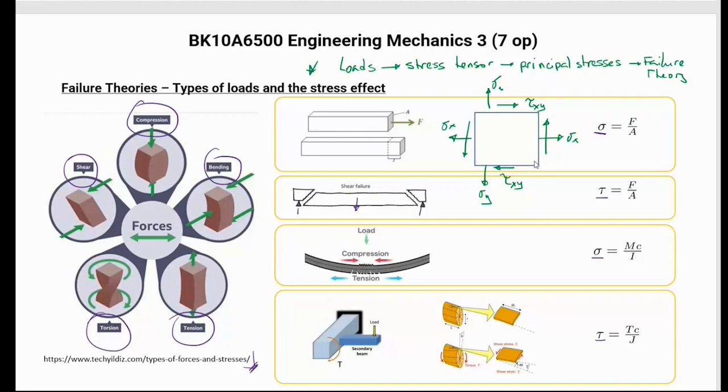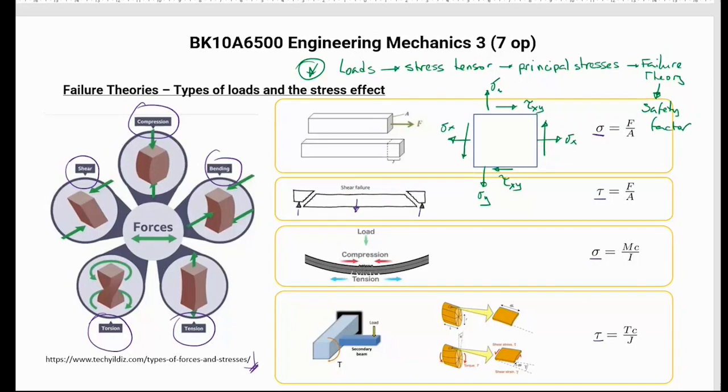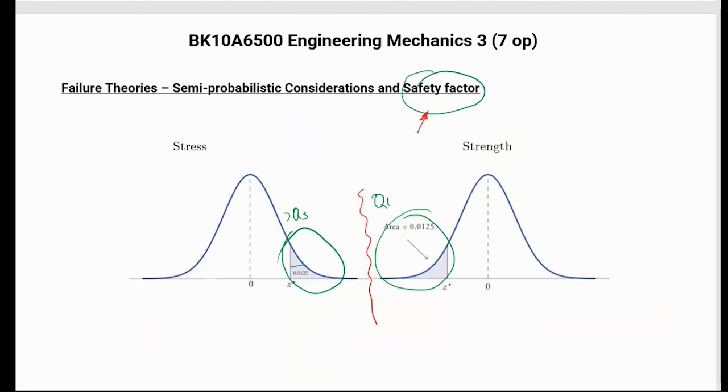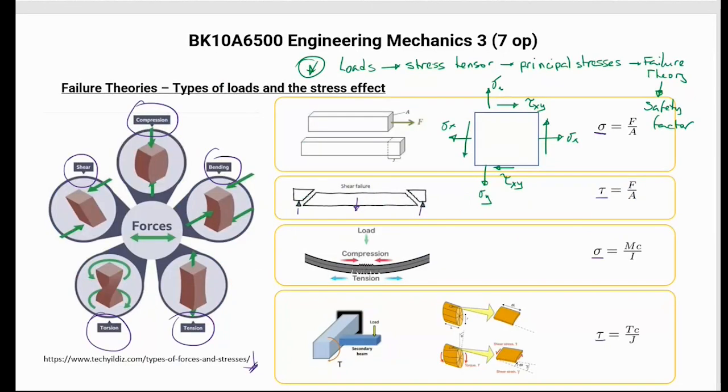And this is the resolution process of any of these problems. Give me the loads, let me calculate the stress tensor, let me know the principal stresses, let me apply a suitable failure theory, and boom. Still, you're going to find in books, they're going to ask, what's the safety factor that it's giving you? And if it's larger than 1 or larger than some prescribed safety factor, then it's okay. If not, it's bad. Even though I mentioned up here that safety factor is becoming not the standard, we are still using safety factors. This is a solution process. If you ask me how I should solve this problem, here you go. Pretty straightforward.